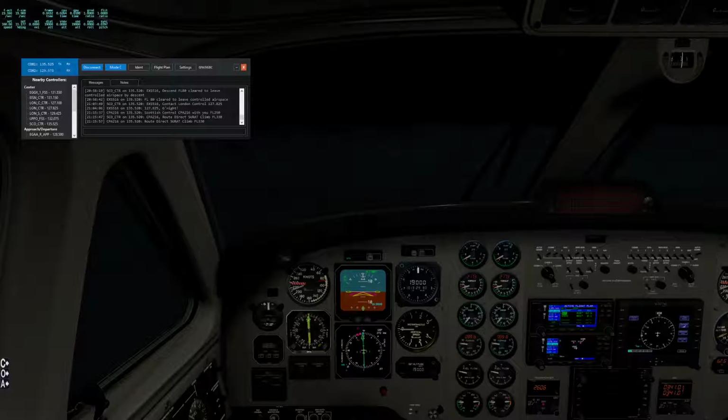it's no different. I've been given 8,000 feet. Unless we were expecting to reach 8,000 feet and maintain that for some time, then I would have to add some extra miles on for descent at the beginning. So in fact, all I need to do is just start my descent at 60 miles as previously planned, except as I'm doing here, set the target altitude to be 8,000.